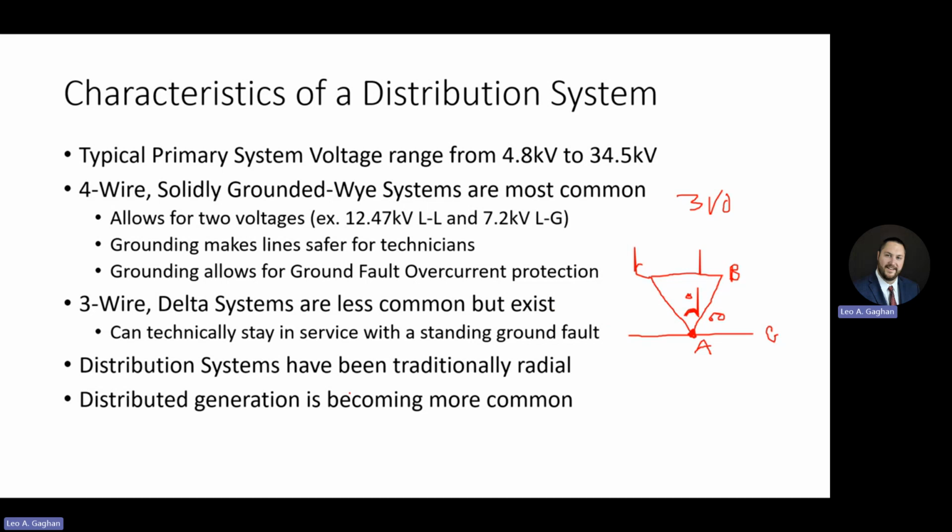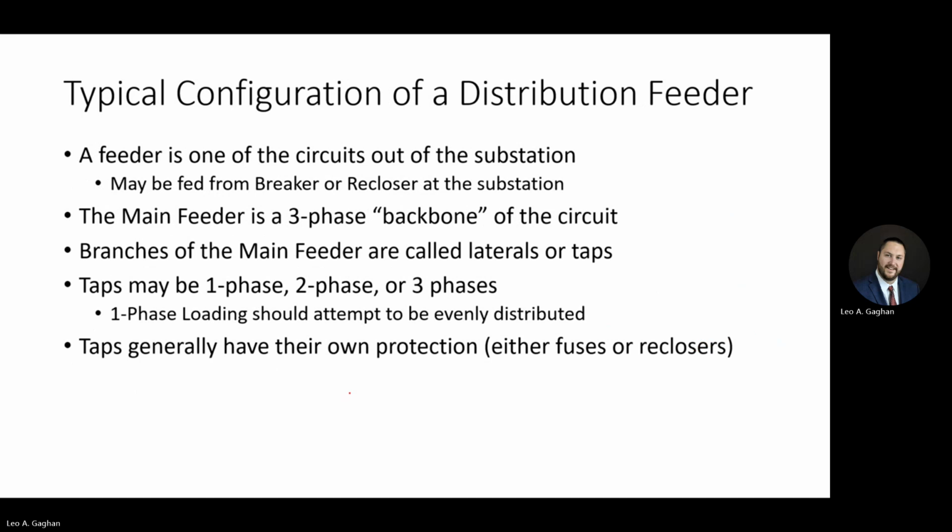So there's a real impact to that. So, typical configurations of a distribution feeder. I think we've got an image after this that'll help. A feeder is one of the circuits out of a substation. At the substation, I've seen it be fed from a breaker with a relay, but also commonly where they have a recloser and recloser controller at the station.